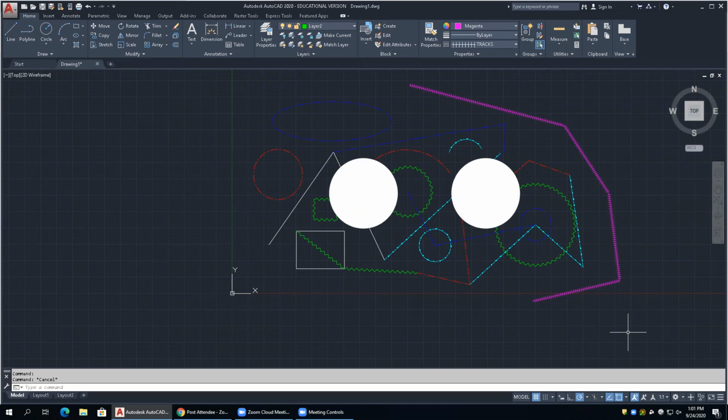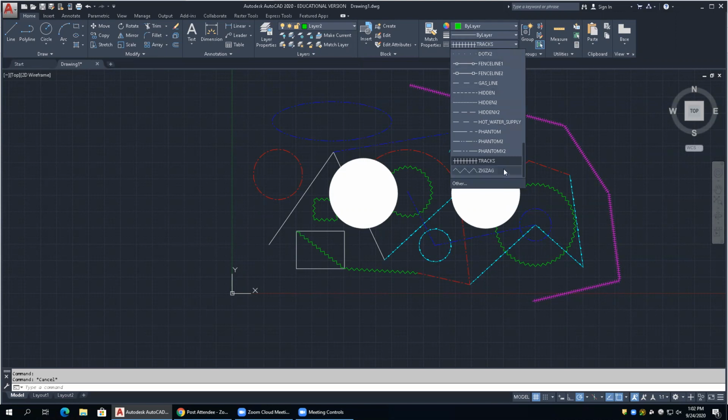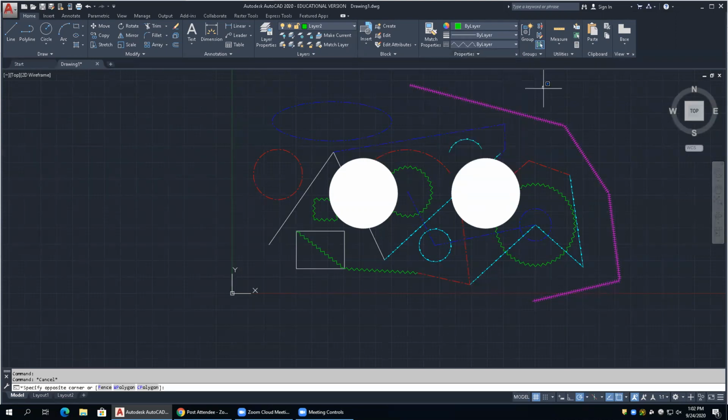This is what we call a mess. You don't want to do this, okay? My suggestion is never set your objects up to specific colors, line types, anything. What we typically always want to do is make sure that this says by layer, and that says by layer. So you typically want everything to be by layer, okay? But notice by setting that up there, that didn't fix these.